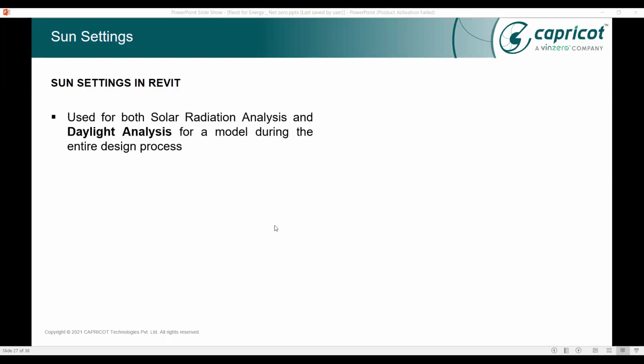First of all, sun settings like shadow analysis. Shadow analysis is actually the main thing. If I talk about it according to the location, the building orientation will be according to that, right? So sun analysis is a major important thing where we go for the sun path direction, right? And this will help you in developing your shading devices, like where the sun shading devices are mainly used, at what orientation we need more shading devices, right? So the shadow analysis is actually needed over there.